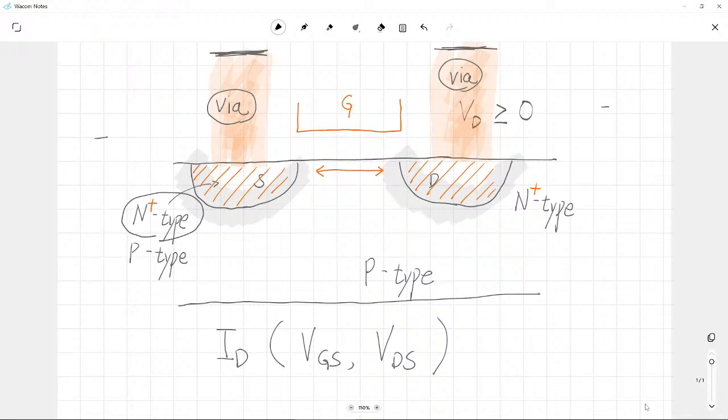Of course, in order to make it as general as possible, we have to introduce other expressions for source, gate, and body or substrate. But what we have assumed is that the gate current is identically zero because we have introduced a perfect insulator for our gate contact.